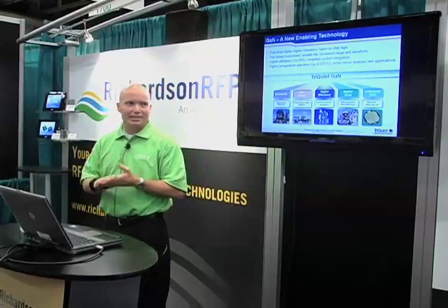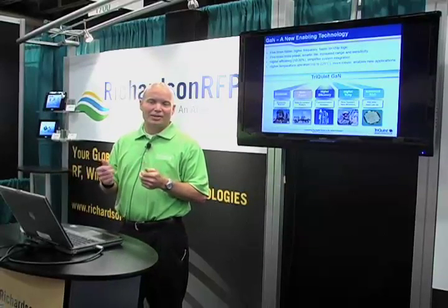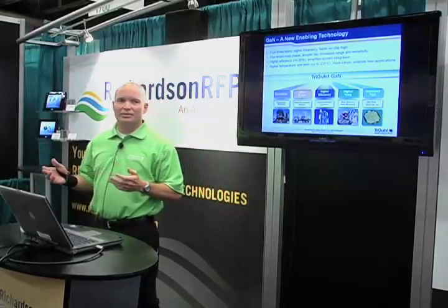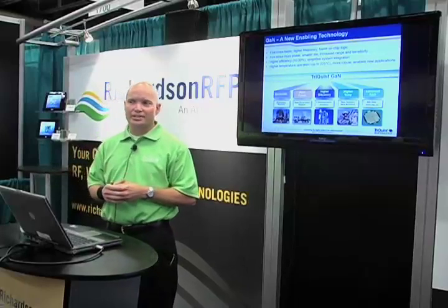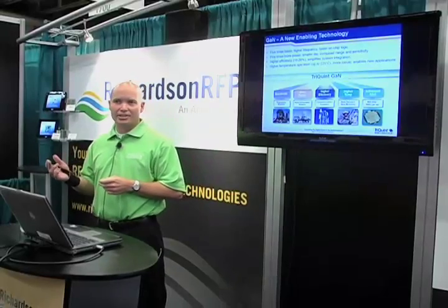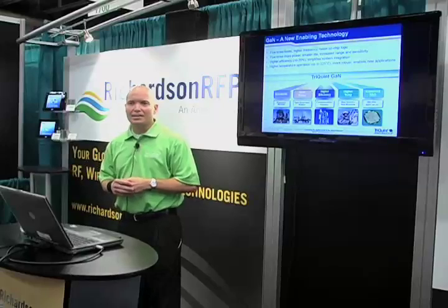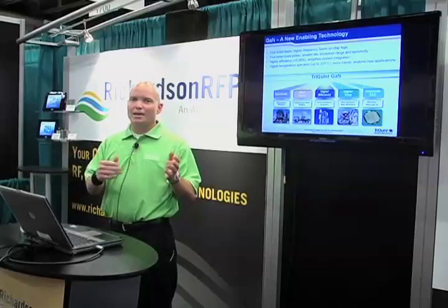The good thing with GaN on silicon carbide, which I'll show in a later slide, is the reliability for silicon carbide is much more than we ever achieved for gallium arsenide over temperature. So where 1,000,000 hours for gallium arsenide was 150 degrees C junction, we can achieve 1,000,000 hours with GaN at 200 degrees C junction, if not higher. And then advanced R&D, I'll get into that in a few slides, where we're basically going higher in frequency, higher efficiencies, thermal management, and I'll get into that in the next slide or two.